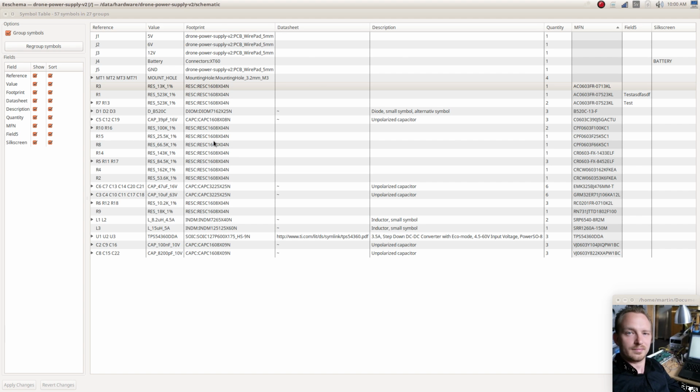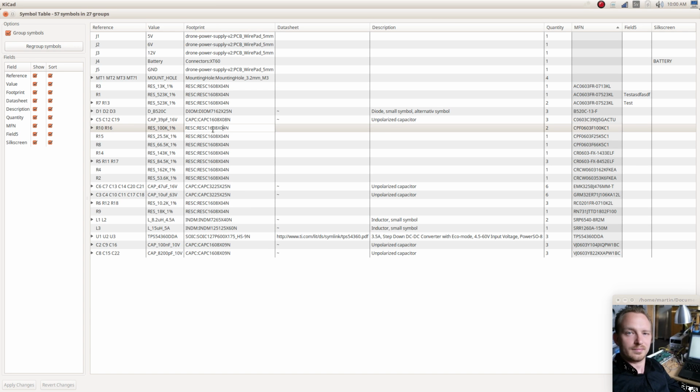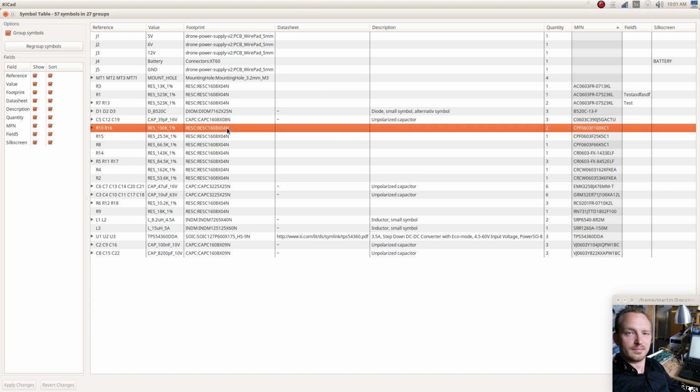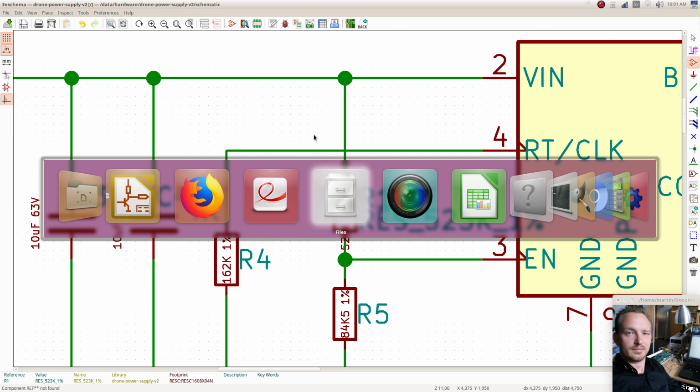And for example, here I've manually entered many of these footprints where I would say, okay, the package has 0.4 millimeter height and it's a 1.6 times 0.8 millimeters chip resistor, right? So then I could just enter this string, and what would be nice in KiCad is if it could generate this automatically, but what I ended up doing is writing a few Python scripts that would generate those footprints for me. But what would be really nice here is to be able to modify this field in the schematic and then to be able to import it back into the library.